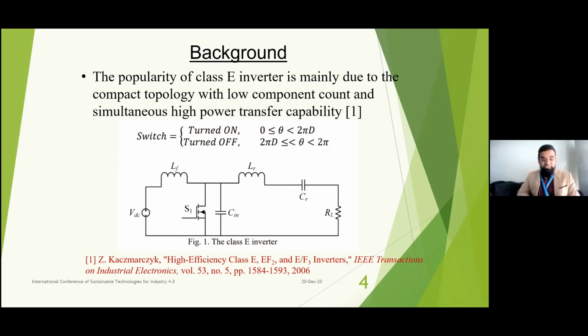So the circuit has basically 2 parts. On the left, as you can see, the input inductor, which we call the DC input feed inductor. And there is a lot of literature on how we design an input feed inductor. Basically, we can make it a very high value to ensure that the input current is DC with low input ripple current, or we can combine this input DC feed inductor with the resonance circuit to operate in the resonance operation.